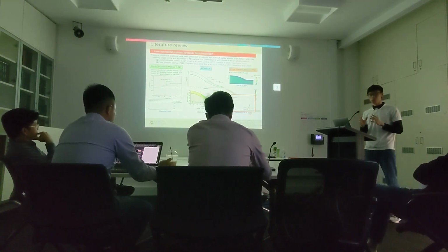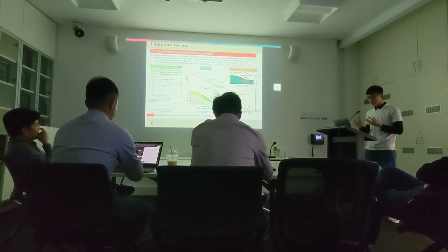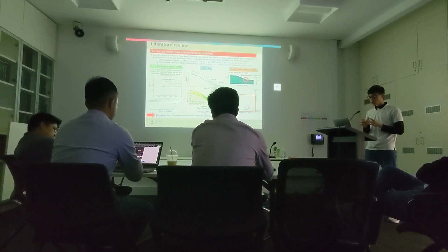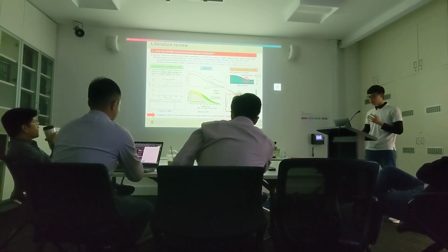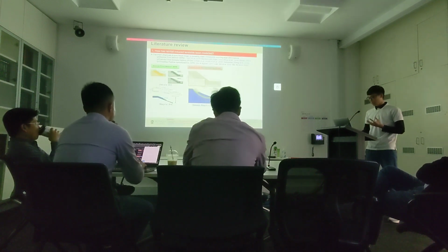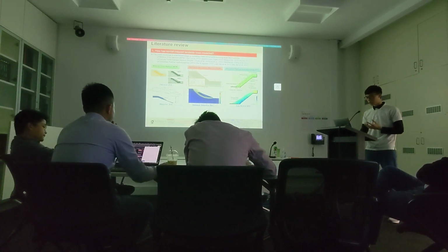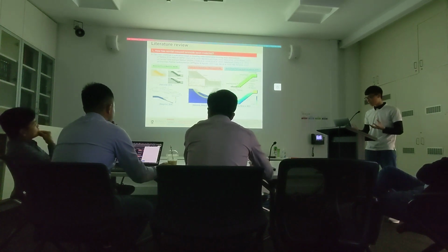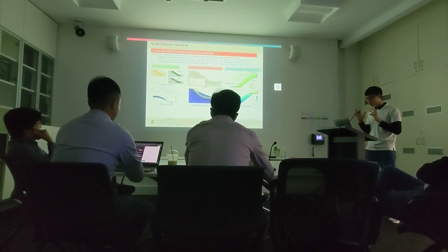So it has been successful in several practical applications, but it should be noted that it has some limitations. The well-known issue is named mesh distortion. The limitation I want to highlight here is that most of the efforts of both have been limited to the failure initial stage, where we have small deformation. So from this point of view, to overcome the mesh distortion issue and simulate large deformation problems, the methods over here, MPM, PFEM, or HVX, the smoothed particle hydrodynamics, a mesh-free continuum method, might be a better choice.